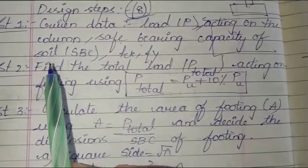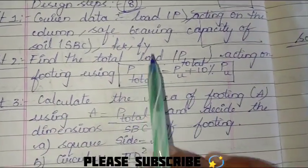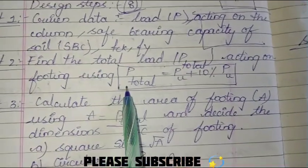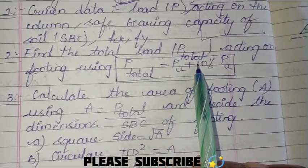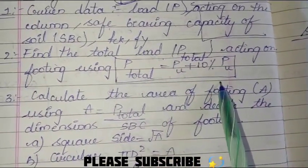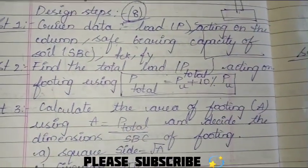Firstly we will be finding out the total load. As you know, we are given the safe load, whatever the load that is acting on the column. We are firstly finding out the total load, that is P total. It is nothing but Pu plus 10% of Pu. Pu is nothing but the given load, the working load.